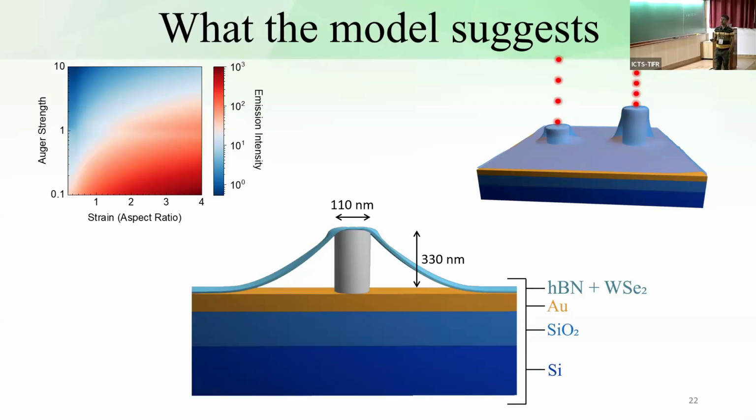So what we do instead is we use a photoresist, a negative photoresist, and we bake it. That gives it enough mechanical strength, and at the same time it's so-called soft enough that it doesn't punch through. So our yield was pretty good. I'll show you some data after this. So this is sort of working well.